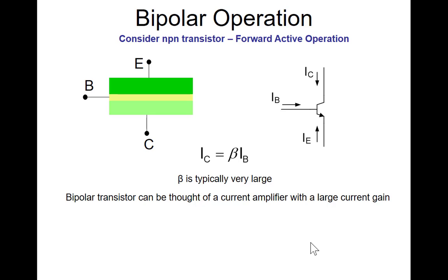Now we trick these devices all the time into having different port variables than they inherently are designed to work with. We will trick, by clever circuit techniques, a MOS transistor to serve as the voltage amplifier. And we'll trick a bipolar transistor into serving as a voltage amplifier as well. The devices are inherently, though, a transconductance amplifier and a current amplifier respectively. Make sense? Devices are transconductance and current amplifiers, but we will make them operate in different ways depending on what circuit we put them in.